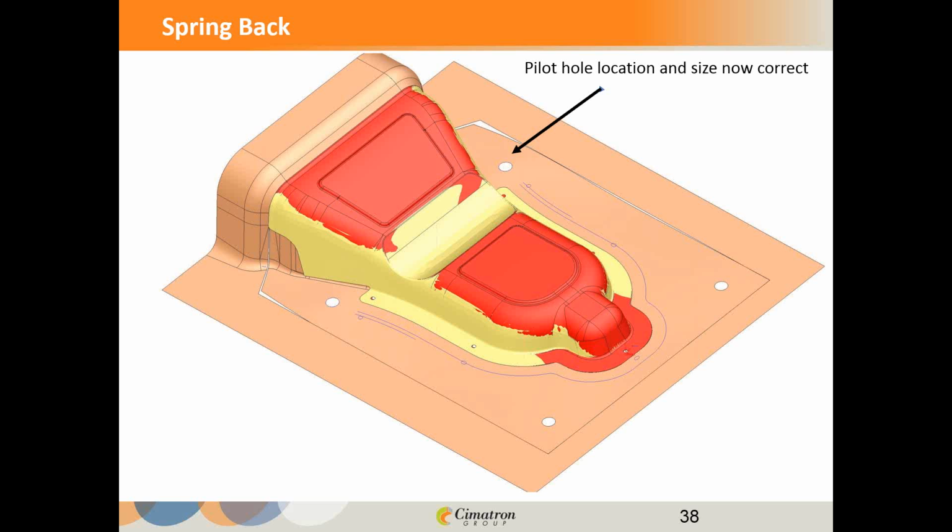So there's a flexibility there that it gives us where I'm not totally redesigning everything. I really need to know those pilot hole locations, and I really need to be sure they're not going to move. So that's a crucial part in understanding how the die is going to hold its form while I do this deformation.